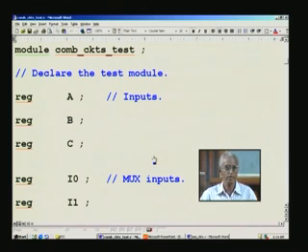So, we may be right now at time 0, and we will move on to the next 10 nanoseconds and 20 nanoseconds and so on. So, we may go step by step, advancing in terms of time. When we do that, unless this is held firmly, you will not get a stable input for your simulation. Therefore, it is essential that you declare it as reg, and if you declare it as any other thing, the tool will complain.